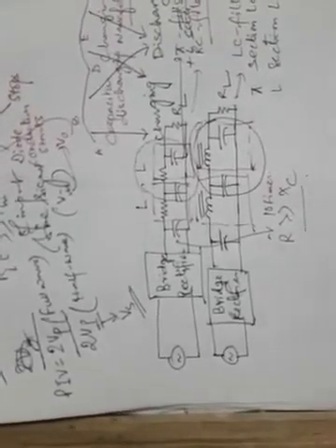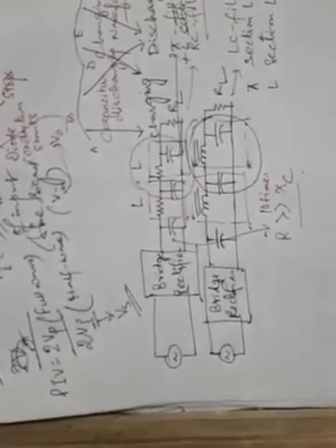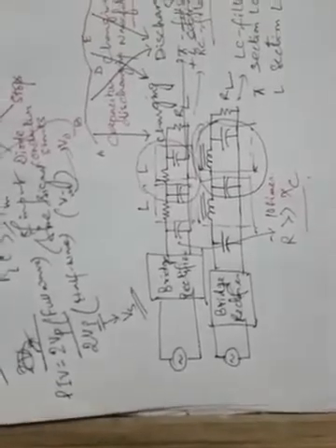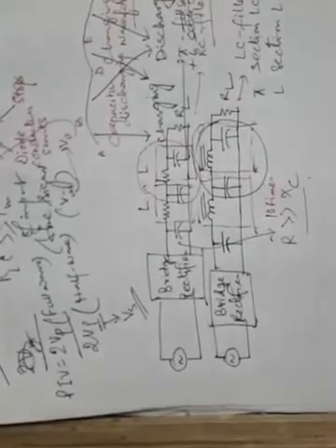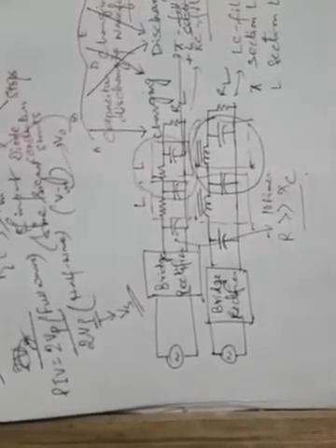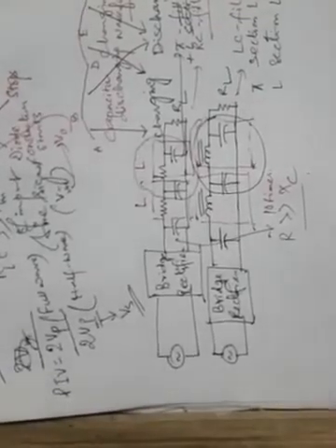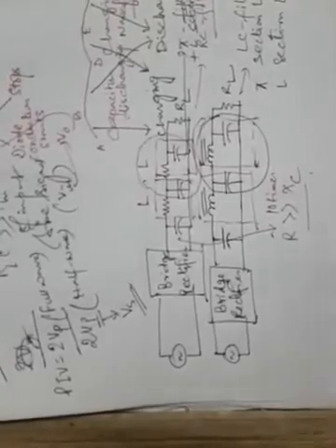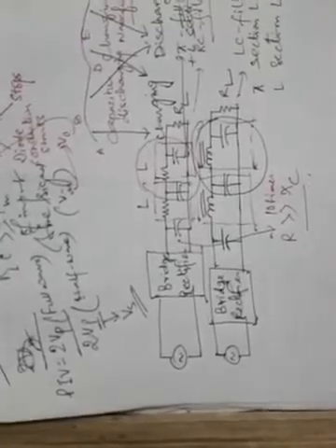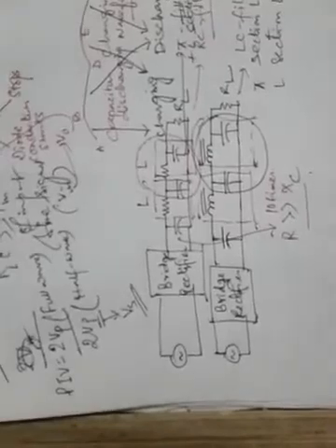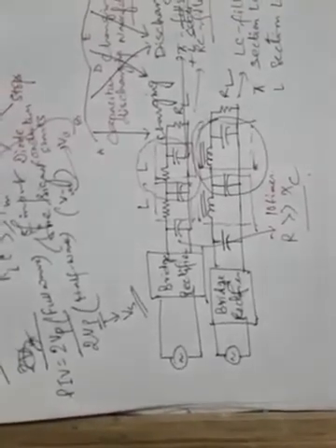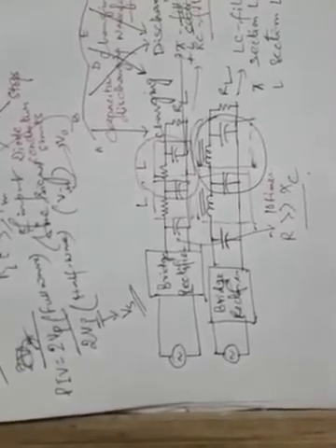But there is a disadvantage in RC filtering. It is because of the use of R. You know, R is a lossy component, and because of R there is always some possibility of signal loss or attenuation by the resistance R in its signal path. So this type of RC filtering scheme is unsuitable for... sorry, I have just told you the opposite. This RC filtering scheme is suitable only for very light loads, that is in case of small load currents or large load resistance, because otherwise if it is high load current, it will mean higher loss for the signal passage through the lossy component R. So this is all about the RC filtering scheme.